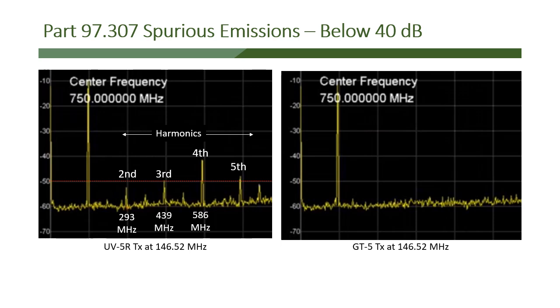Whenever you're on frequency, you want to see that there are no harmonics coming out of the antenna because of bad filtering in the transmitter. And so you won't find this on your test, but I just want you to understand it, because when some people say to you, well, I own a Baofeng UV5R, and you should buy one, the answer is it's not a bad radio. I won't complain about the radio, except this one factor: many of them are not legal.